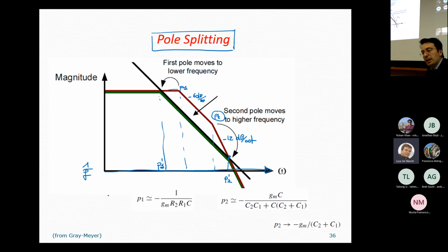So here you see what is the effect of increasing the transconductance on the pole position. Okay. So if you choose a transconductance value which is 1 microsiemens, then you have the first pole here, second pole here, and then the 0. Okay. If you choose a transconductance which is 10 microsiemens, then you have a better pole splitting, and the 0 is shifted at even higher quantities.